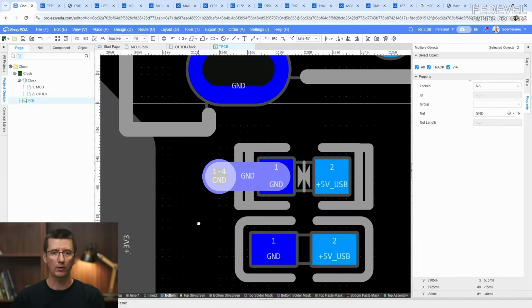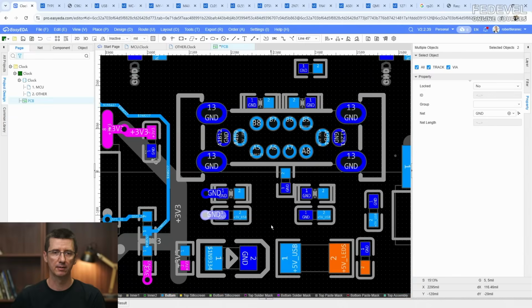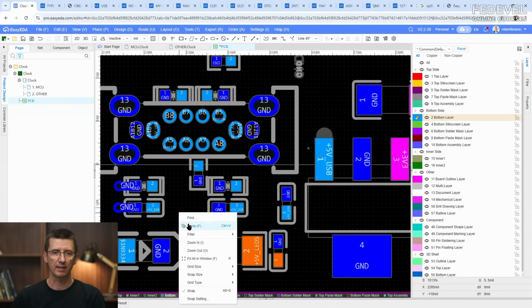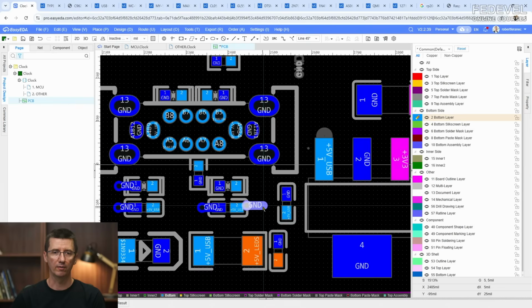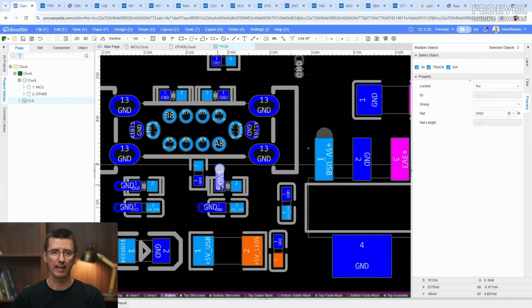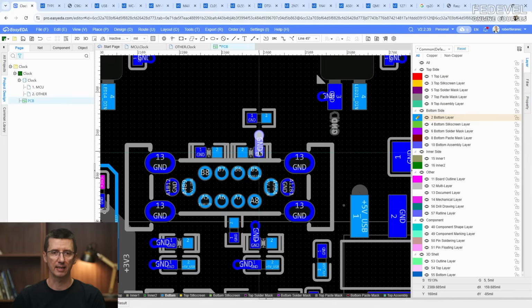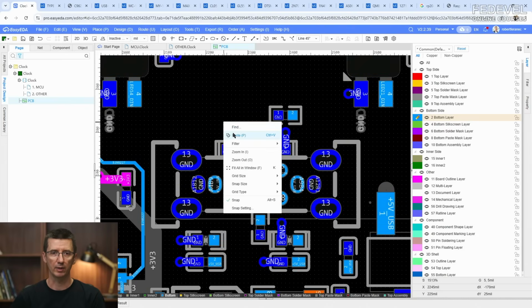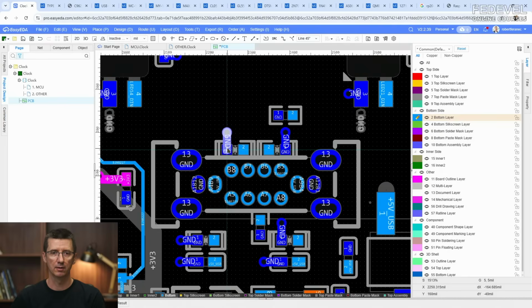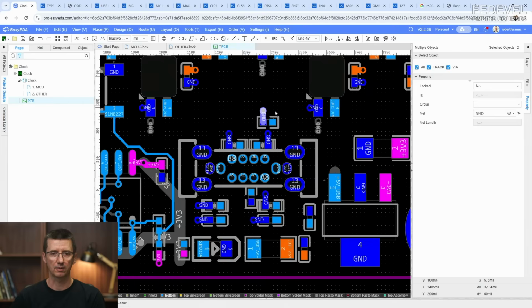Put there all the vias before you actually start drawing signal tracks. It's very helpful because then you will know where you need vias and you can go around them. If you would route signal tracks first, and then if you would be placing vias, then you may need to reroute many existing tracks. So always place vias first, and then do the layout, then connect the signals.